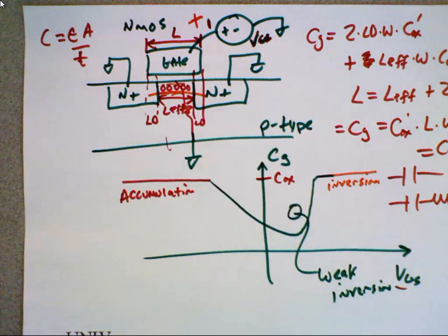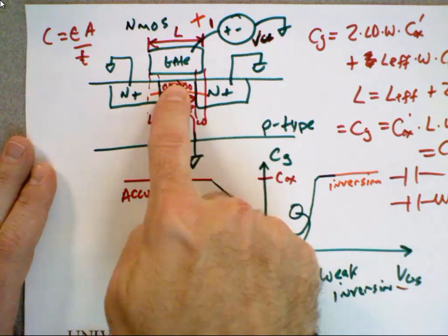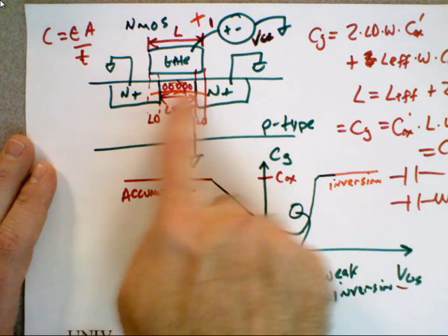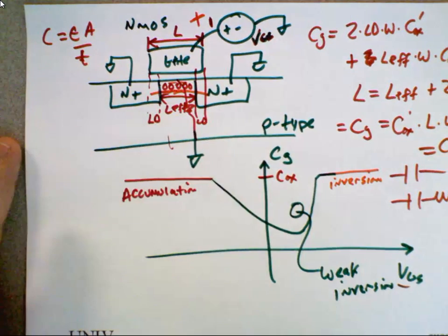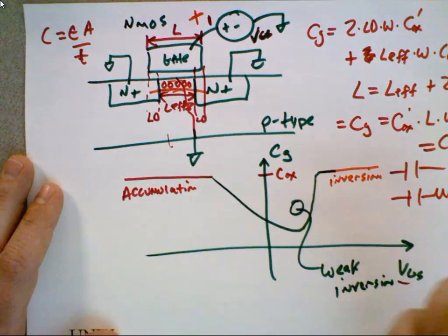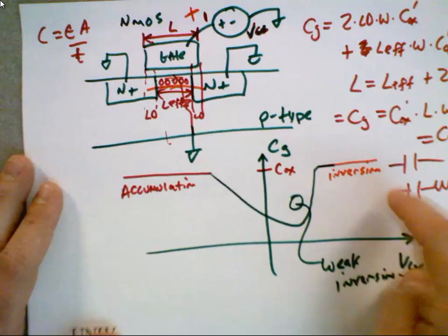Yeah, we don't have a lot of electrons there. It's inverted. It's not p-type. We've applied a positive potential. We pulled some electrons underneath there, but not a lot. So there's still the potential for conduction there. All of those calculator circuits and wristwatches and solar-powered things, they all operate in weak inversion, which means they have very small currents. They don't need much power from the solar panel. So they're operating in this area. Processors and your cell phones and that stuff eats power. It operates in strong inversion.